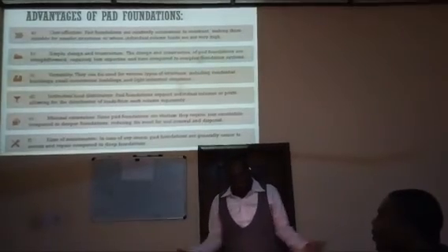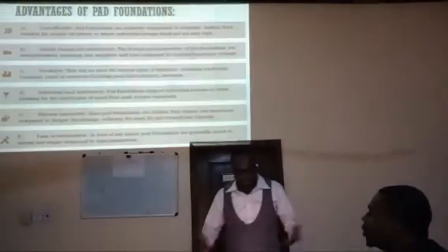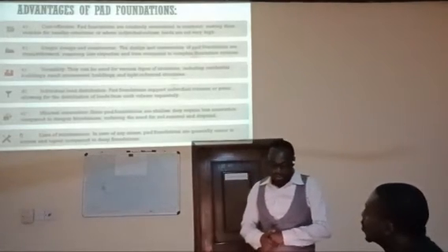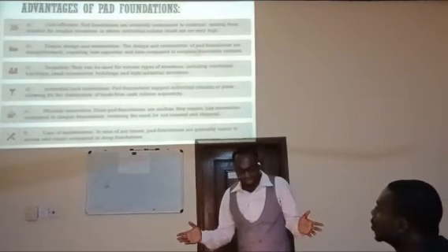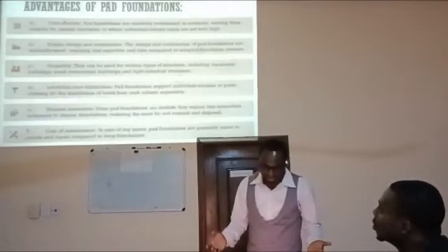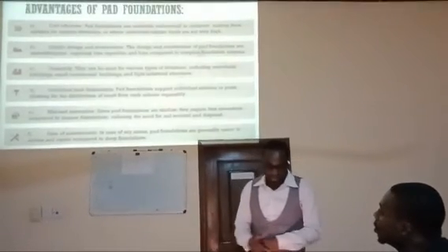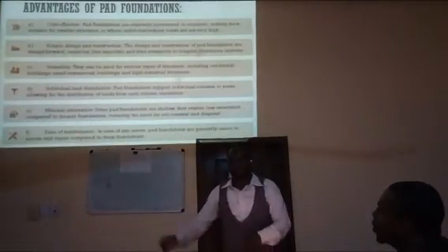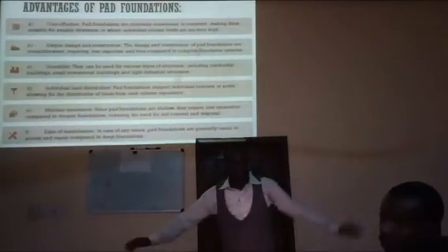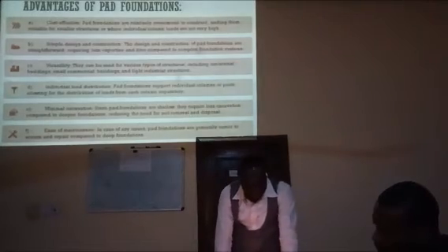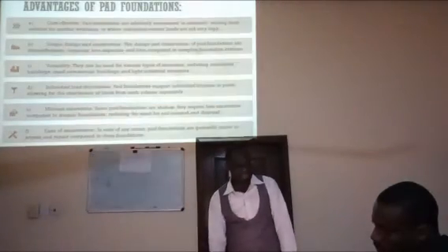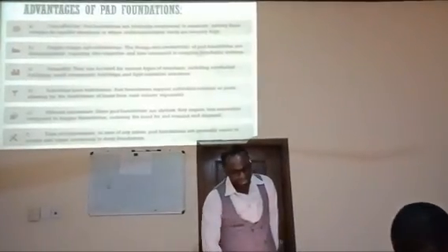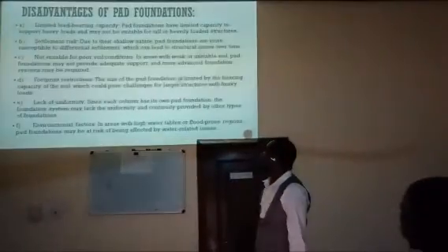What are the disadvantages? Next page. Limited load bearing capacity, just like the strip foundation, because they are all types of shallow foundations. Their load bearing capacity is highly limited because there are some loads that you cannot place on them. They just cave, they just collapse. There is also risk of settlement due to their shallow nature. Okay, so they are not suitable for poor soil condition. When the soil is not good, don't even think about pad foundation. You can be thinking of strip foundation or any other one.